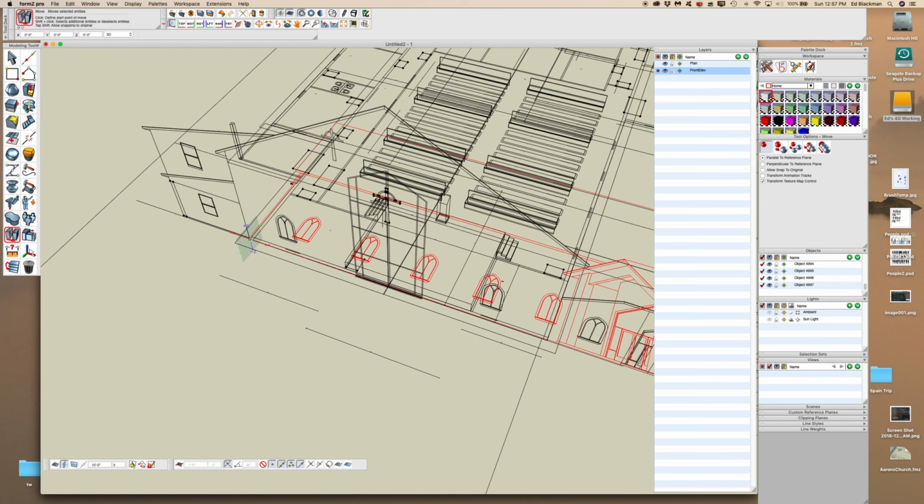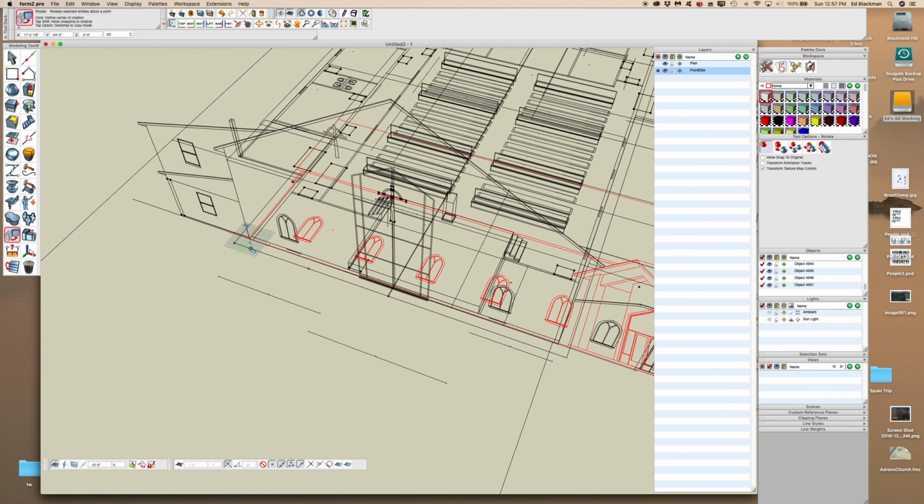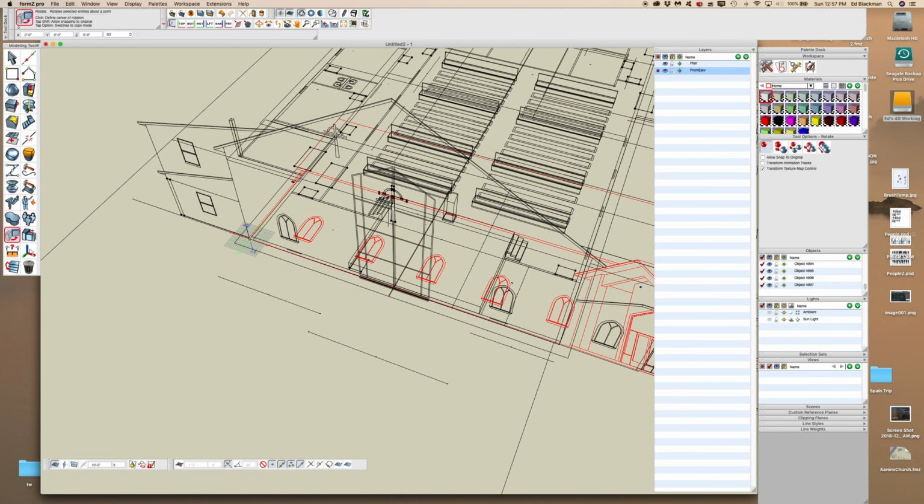Okay, now this one, we've got to rotate it around in plan view 90 degrees, and then we've got to rotate it in two rotates, right? So go down here and click in the plan orientation. Go back up here and click the rotate tool again. Zoom in a little bit, make sure you're on that intersection right there. Go out here. Now, let's just show.